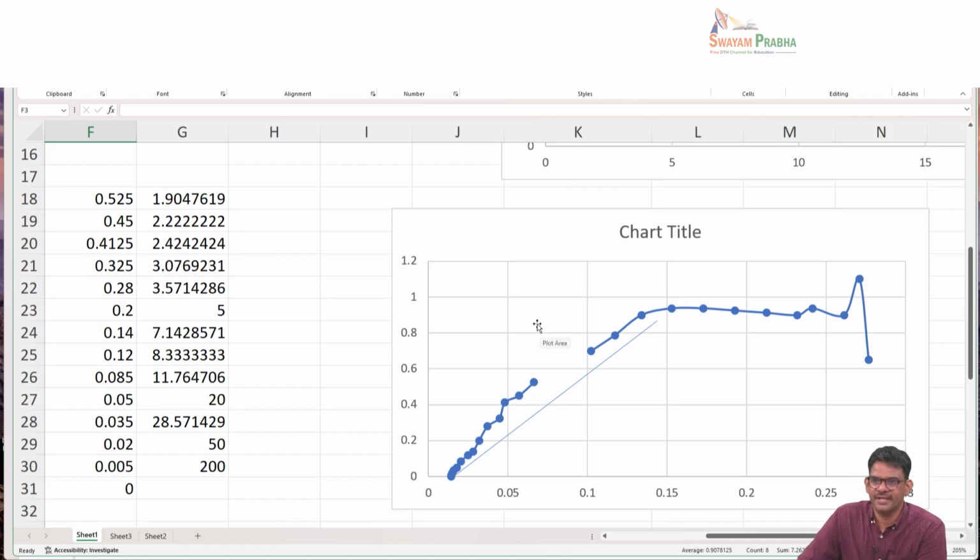It is solid controlled drying, exactly. In the unbound moisture drying, which is the constant drying rate, the drying is controlled by the gas phase. So if you change the gas phase property, it is going to change, whereas the falling rate is broadly controlled by water diffusion inside the solid. Whatever you do on the gas side may not affect it so much. It is driven completely by the internal mass transfer within the solid. So we can fairly assume that it is not going to change much when we change the drying conditions outside. So that is the assumption that you are going to make, and using it you can make this calculation.